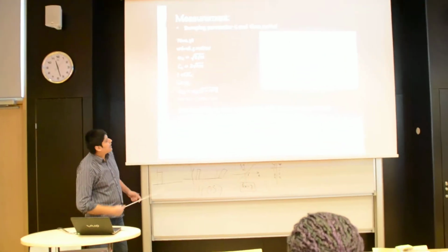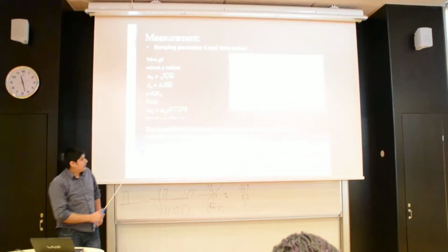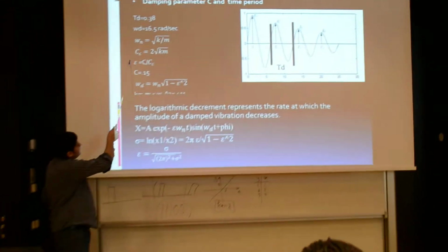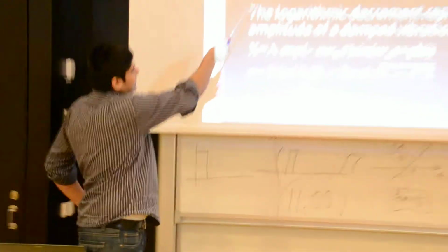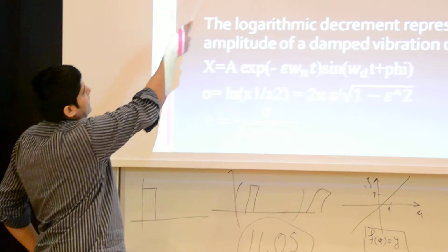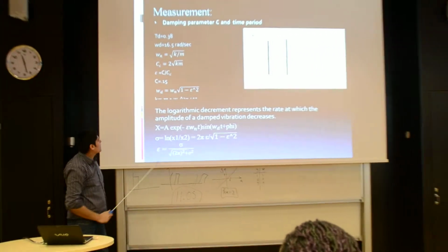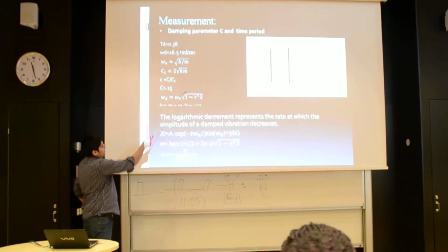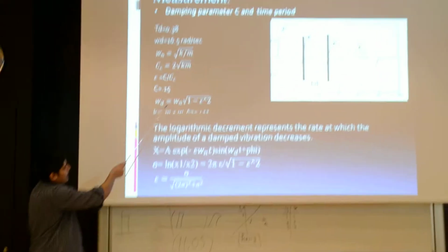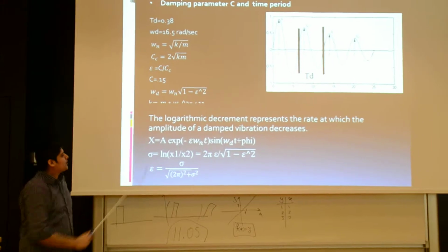And that one is our main part, to calculate the damping parameter C. So we just calculate damping parameter C from the damping factor, and this Cc is here for critical damping. We can find it from this relation, the square root of K times M, and this one is the relationship between the undamped natural frequency and the damped frequency. This one is the relationship between them.